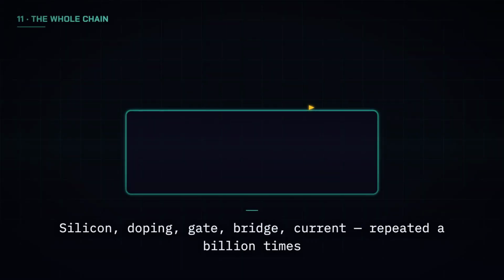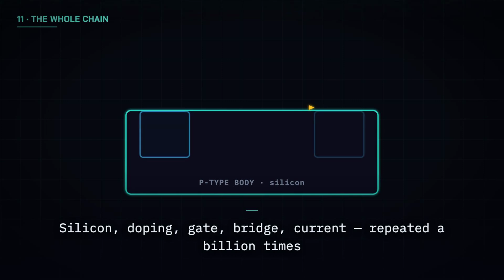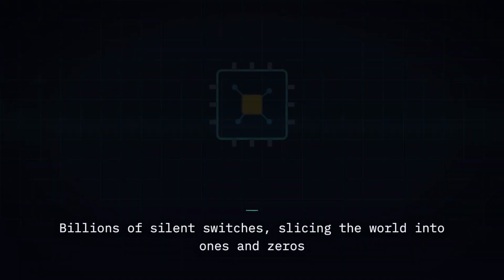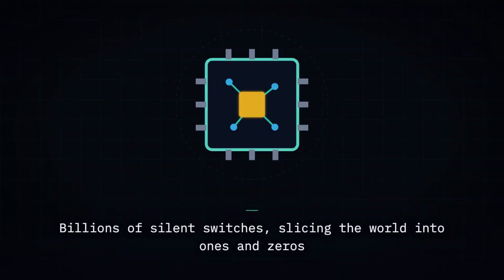So let us trace it once more. We start with silicon, the undecided middle ground. We dope it, making N-type pools inside a P-type body. We lay down a source, a drain, and a hovering gate above the channel. With no gate voltage, the holes wall off the path, and the switch sits off. Add a small voltage, and electrons rush up to form a bridge, so current flows and the switch turns on. One valve, no moving parts, repeated 1 billion times. A whisper of voltage, a bridge of electrons, a perfect yes or no.